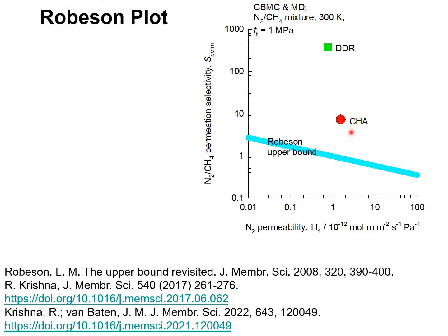For both Chabazite and DDR zeolite membranes, we performed configurational bias Monte Carlo simulations for adsorption of nitrogen methane mixtures, along with MD simulations of self-diffusivities in nitrogen and methane mixtures. By combining the data on mixture adsorption and mixture diffusion, we can determine the nitrogen methane permeation selectivity